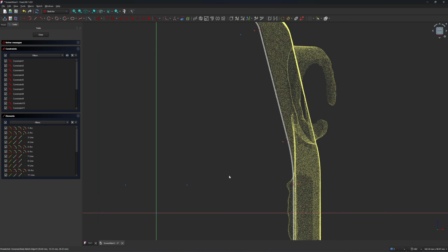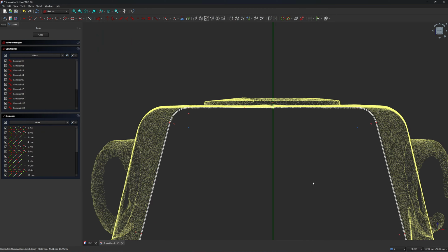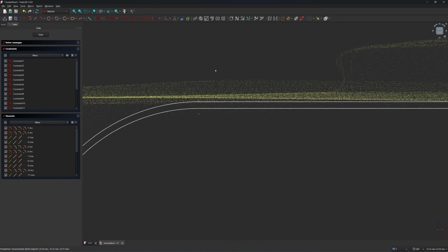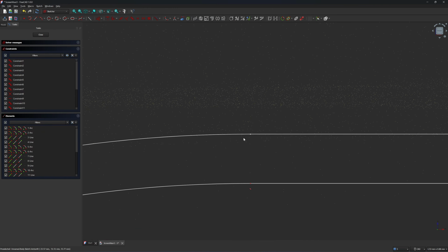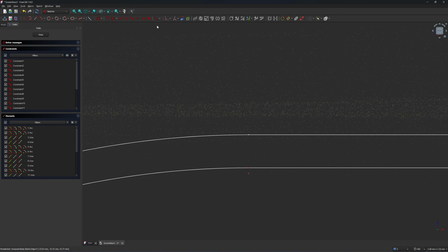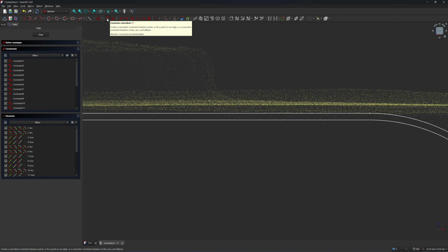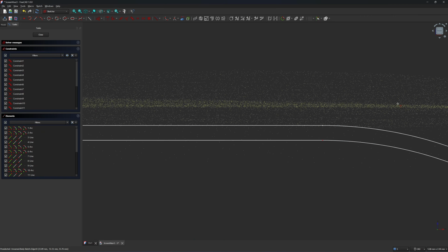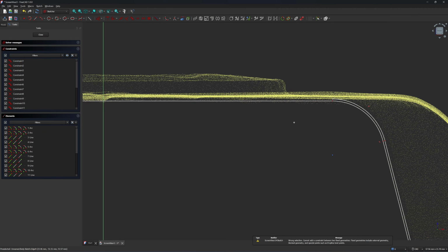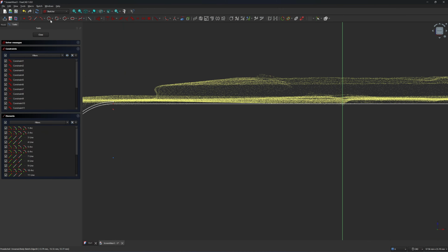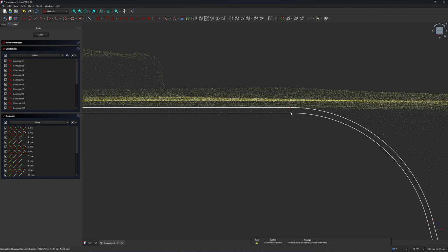So there's extra work that you have to do because I don't have to do this when I use the Inventor. And you see these two lines are not connected, because if they connect, they will turn into orange color. So you need to lock one of the lines and this line, and then you constrain it. Okay, I'm gonna delete this line and then I'm going to draw a new line. Okay, so now it's connected.